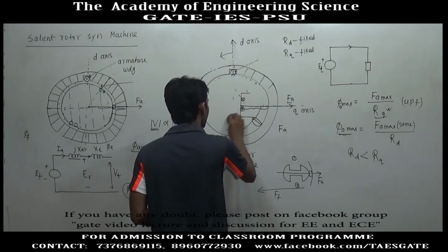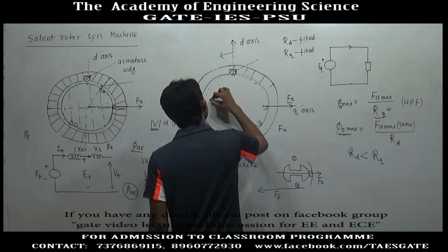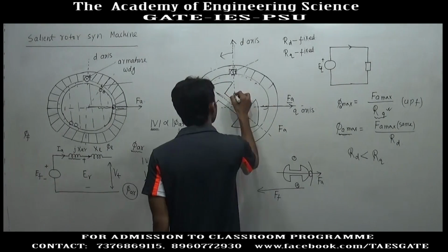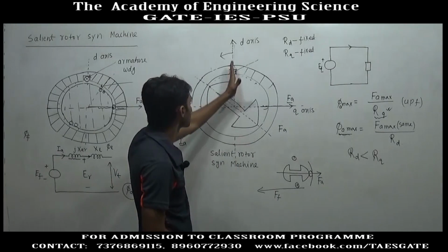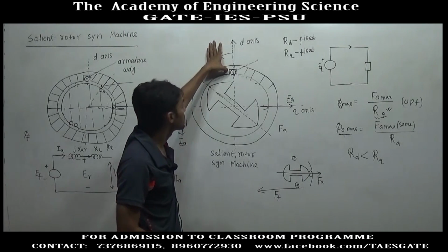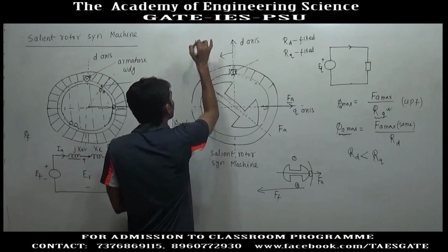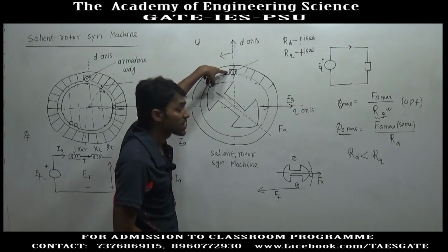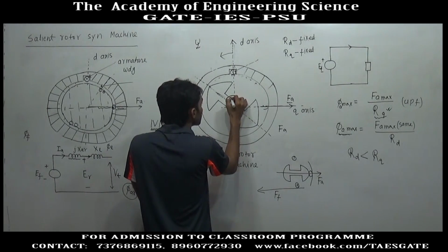Suppose for a phi power factor, this was the maximum EMF position of the rotor. In this rotor position, the EMF generated in this conductor was maximum, but the load is phi angle lagging. So, after phi angle, current in this conductor has reached the maximum value, but after phi angle the rotor was rotated phi angle.